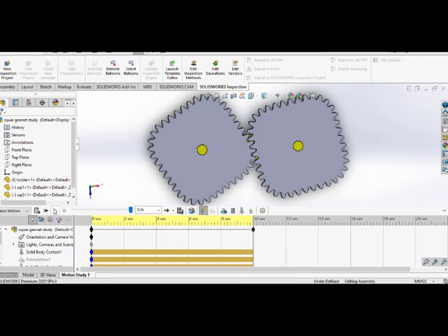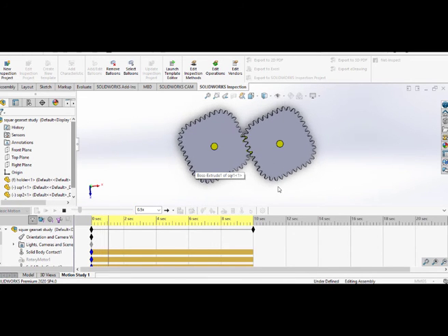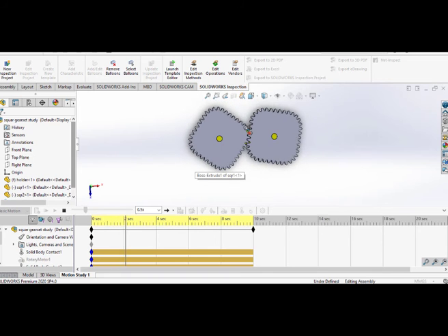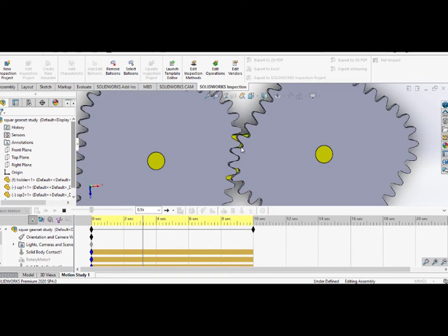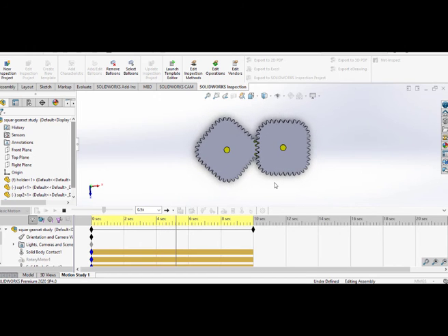The second step is the generation of the teeth profile for each tooth and saving the coordinates of each tooth into text files, wherein the teeth on the straight part of the centrode are rough ones and the teeth on the round edges are circular ones.